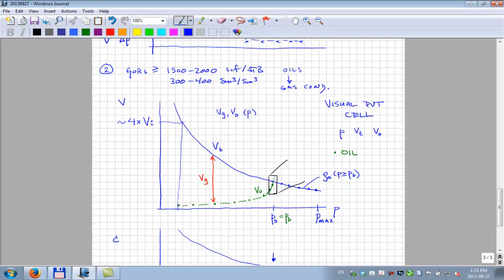Finn Haven's not here, but his dad identified a fairly serious systematic problem of this particular thing in one of the Gulf of Mexico laboratories when we were doing some studies there a few years back. A very systematic change in the reported oil volumes, basically a constant factor, brought everything into consistency. After 3 or 4 laboratory reports looking at that data, we identified this has to be a systematic error. They went into the lab, checked their procedures, and found that there was some calibration error with the liquid volume measurements.